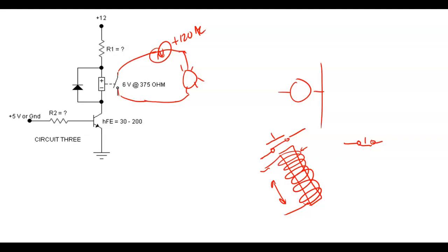And that's another real nice thing about relays. The contacts and the coil can be completely isolated from each other. So it means I can control this relay over here, and I could be controlling DC on one side, AC on one other side. I could have AC relays.